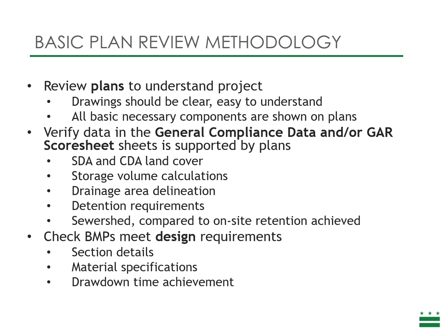Some items that are checked include the site drainage area, the contributing drainage area, and their correlating land cover, the storage volume calculations, drainage area delineation, detention requirements, and the sewer shed. Plan reviewers will also check that each BMP or GAR element meets the design requirements as stated in the guidebook.